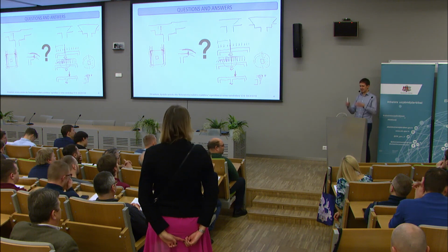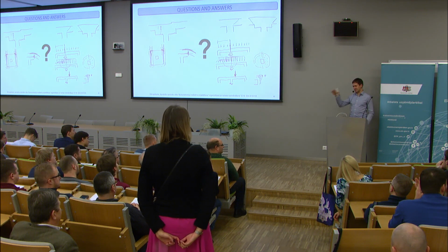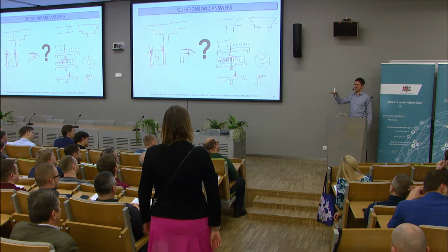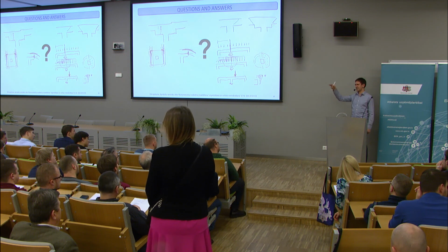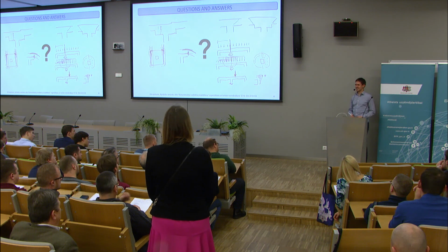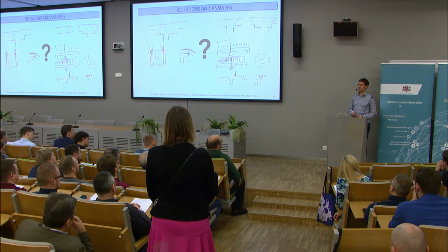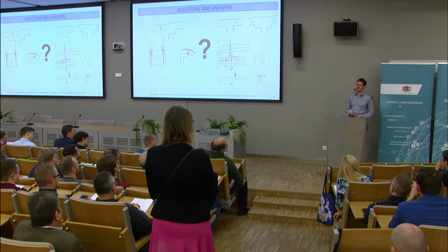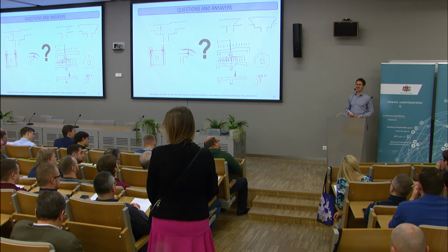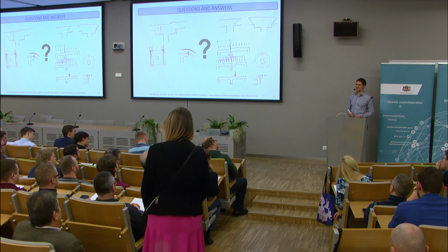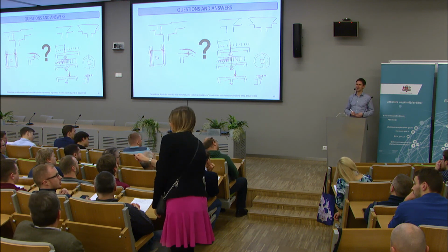But the problem is that if you have point supports, we never put enough reinforcement. We actually do some redistribution because it gives such high peaks that it's not practical to reinforce against them. So even if we do finite element analysis, we do use theory of plasticity and redistribute forces on our own.